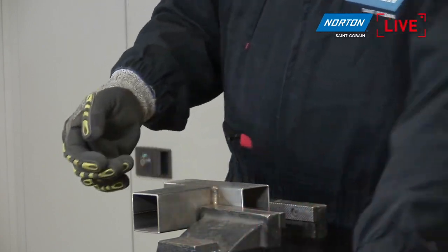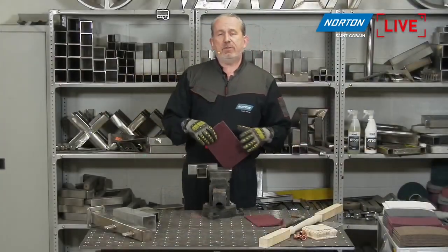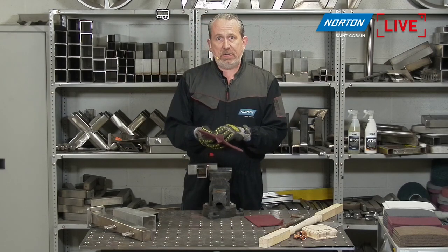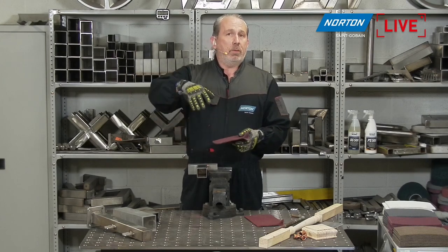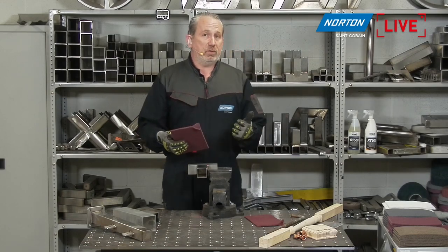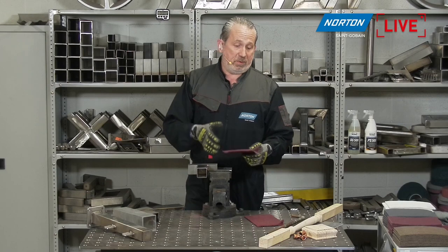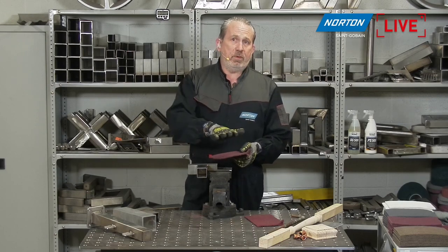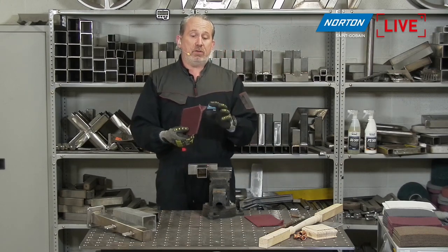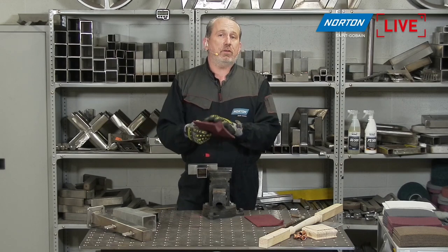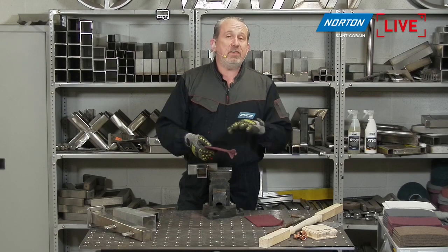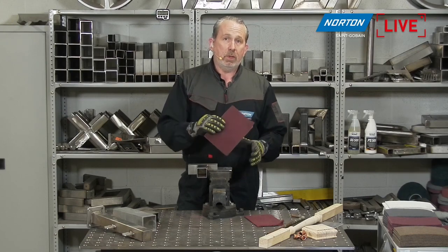And the reason I'm doing that is to show the two different ways that companies manufacture these products and how we actually get the abrasives and resin inside here. A lot of companies just spray a mixture of abrasive and resin over the material once it's manufactured. But we do two things. We do the spray, just as I've said before, but we also do a dip. So we dip the product inside a slurry of abrasive and resin to make sure we've got maximum penetration of the grain inside the material, not just on the surface. That makes the material, as it wears down, obviously last a lot longer because there's abrasive inside as well as just the top and the bottom surface on that.